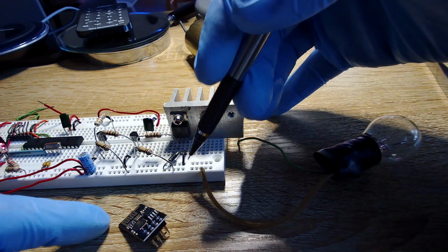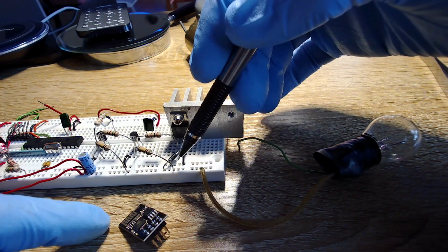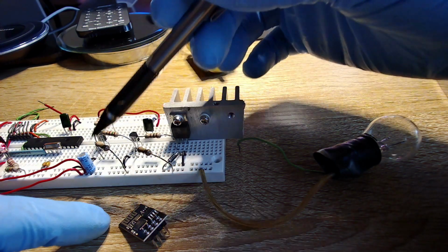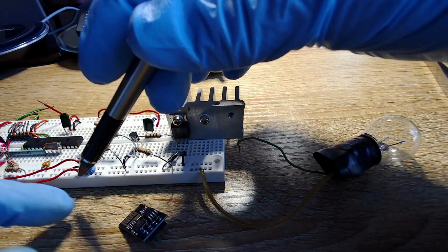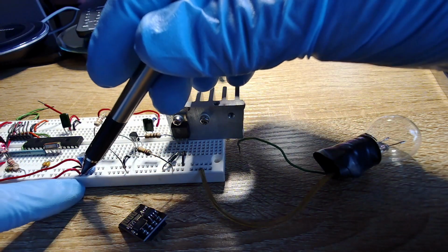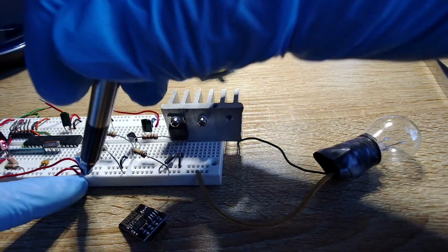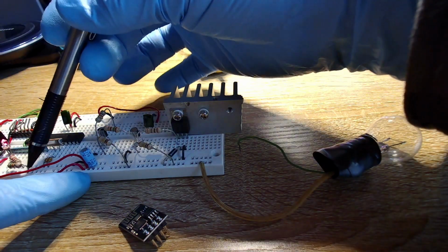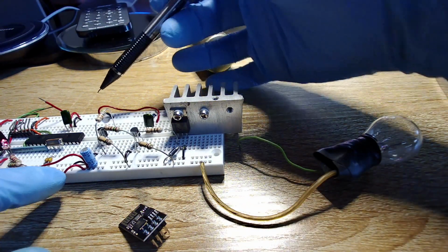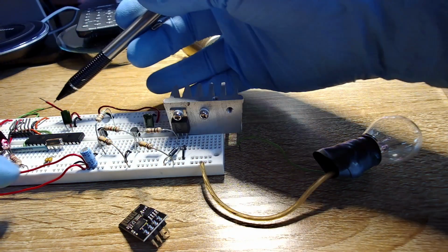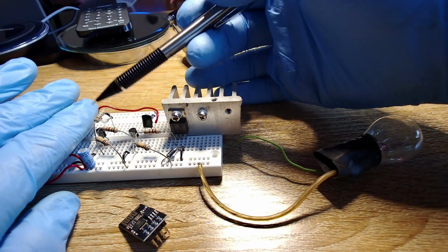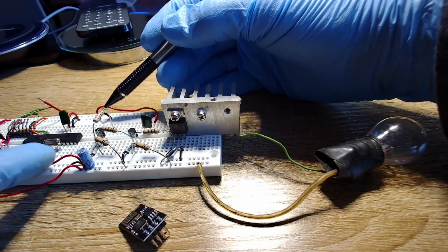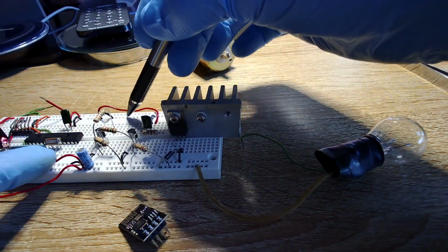If you're familiar, and you probably are familiar with breadboards, let me review real quick. On the outer edges of the board is where we typically put our power. This board isn't marked. Some boards are marked, so I have the positive on the outside. What I have here is this section up here is actually 13 volts, and the whole rest of the board is 5 volts at the positive. And it's jumped back here, behind here where you can't see it. And remember, ignore this circuit over here that I'm hiding. The ground is ground. So the inner rail on both sides is the ground.